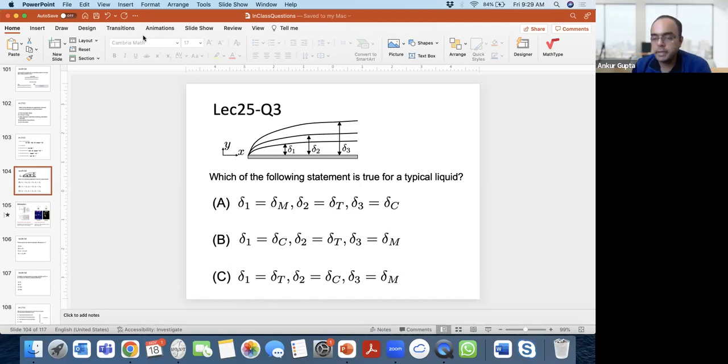So there are three boundary layers which we were discussing that can happen over a sphere. I've just zoomed in again to X and Y. Which one do you think will be the smallest, and which one do you think will be the largest? And as a hint, think about the momentum diffusivity, thermal diffusivity, and mass diffusivity, species diffusivity.